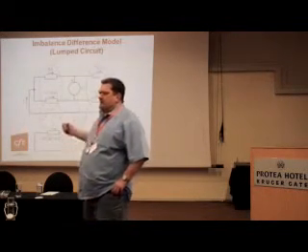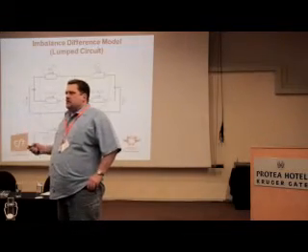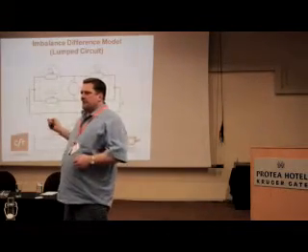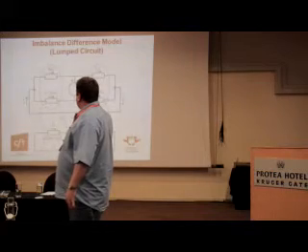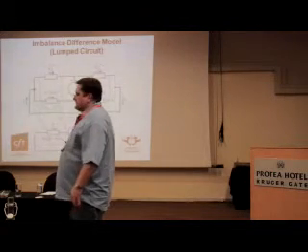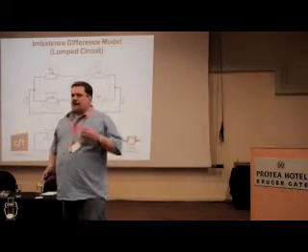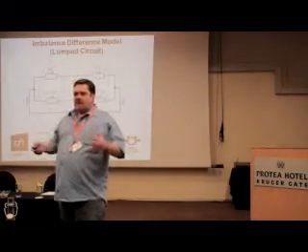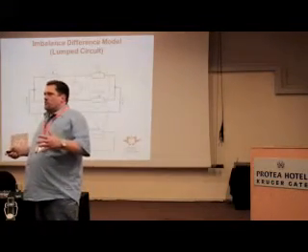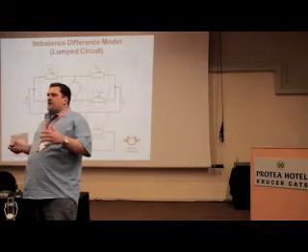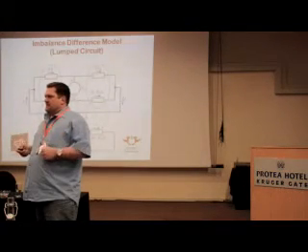It took me a couple of months and years to really understand this, but after a while I got used to it, and from a lumped circuit approach, I can tell you today where common mode comes from. The long and the short story is that common mode comes from unbalance in a system. Okay?